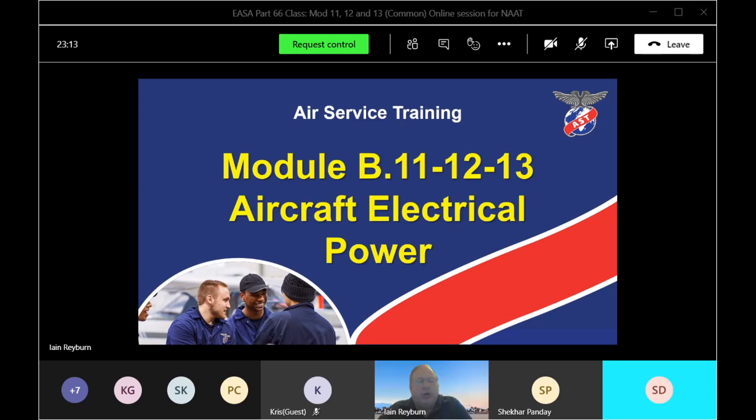Right, so the current is going in the reverse direction. Agree with that? Yeah. So now, if 1 amp flows back into the TRU, the reverse current protection operates and will remove the TRU from the bus bar. Okay, happy with that, Chris? Yeah, good.